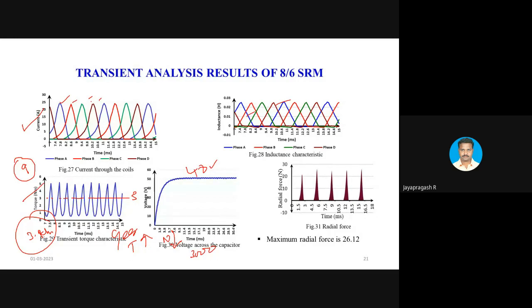Okay, I'm just saying approximately, you can properly choose the gear ratio. Okay, it is most important. Because already we are passing 20 amperes of current through the winding. For this itself it needs a large conductor area. To produce 9 Newton meter without gear, it needs a large conductor diameter, which cannot be accommodated in the space available in the stator circuit. So by avoiding all these complexities, we use this.